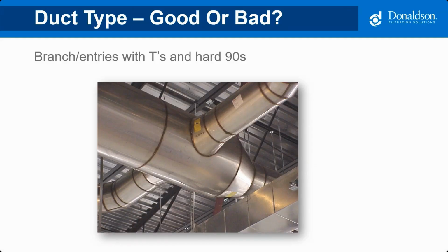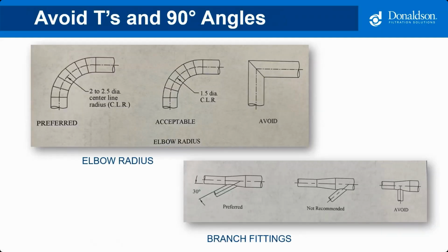Smart group. So if your elbows are mitered at 90-degree turns, all that air, you've probably heard this 100 times, it's going to follow the path of least resistance. So it doesn't have the ability to slow down and then speed back up. Instead, it slams into the back wall of that miter, creating turbulence, and the air coming into it faces more resistance. Turbulence equals more energy consumption or higher static pressure. So again, more expensive fan, larger ductwork, higher operating costs.